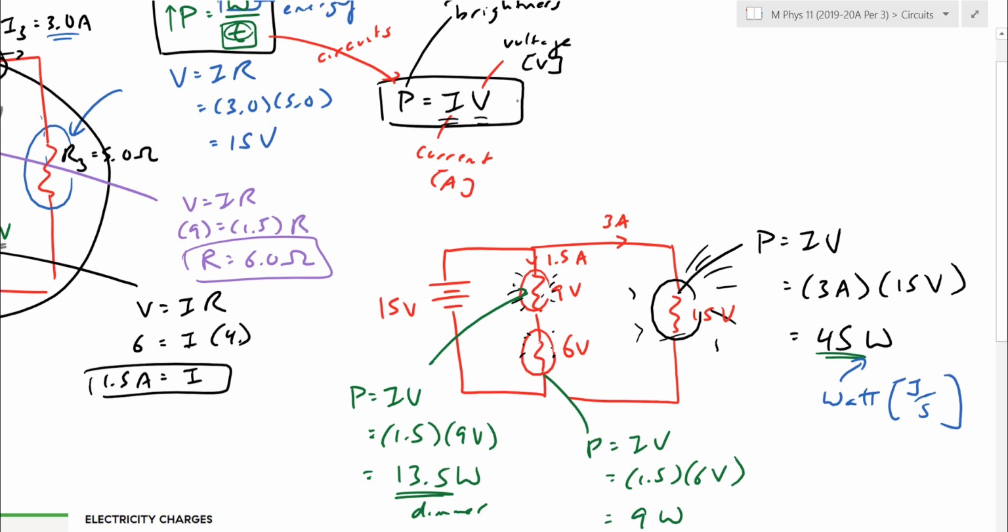What you can do here is say, well, what if I subbed in Ohm's Law instead of V? What if I thought of that as I times R, which is why power can also be worded as I squared R. So if you happen to know the current, I'm actually calculating the voltage if I take the other I and multiply by the R.